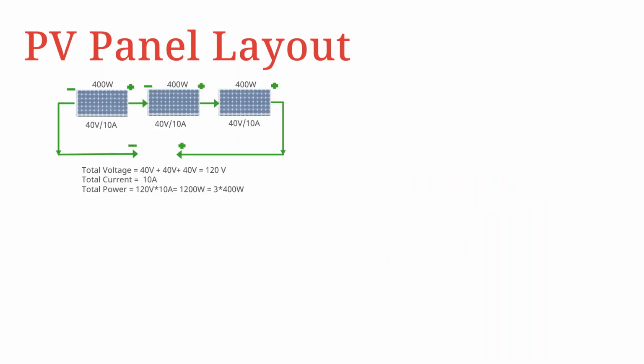So let's start with a series connection of 3 panels, as you can see, all with 400 watts capacity, with an operating voltage and current of 40 volts and 10 amps respectively. The total voltage, since they're connected in series, is going to add up, because the voltage drop across one panel is added to the voltage drop across the other panels. So in this case, it's 40 plus 40 plus 40, which gives us the sum of 120.